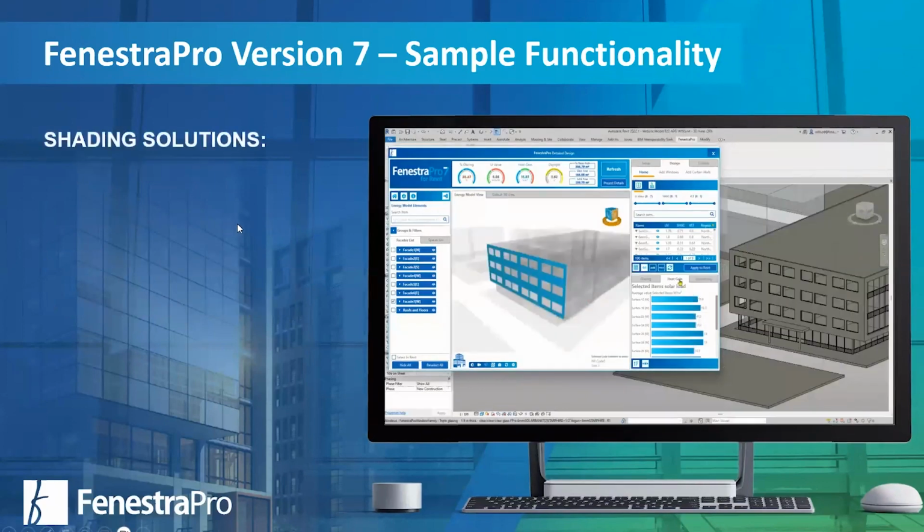Similarly with shading, during the conceptual design stage, you can use the application to establish the optimal depth of a canopy, for example. So to achieve that 25 or 20 watts per meter squared, it'll tell you what that optimal size of the canopy is. So in other words, it stops you over designing shading within the process. Or you can look at alternative shading solutions more in the detail model by creating mass objects outside the model, applying that to the model and looking at the impact it has.